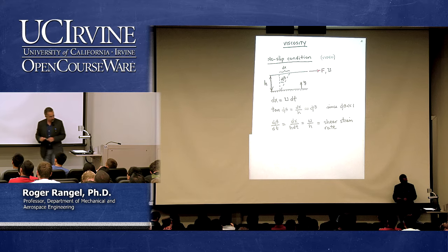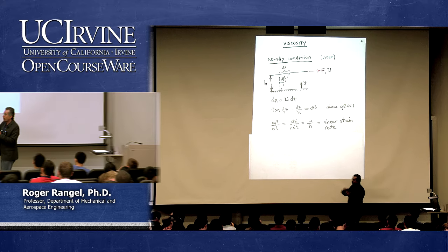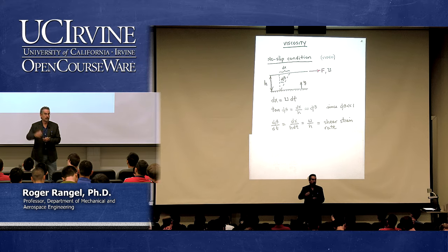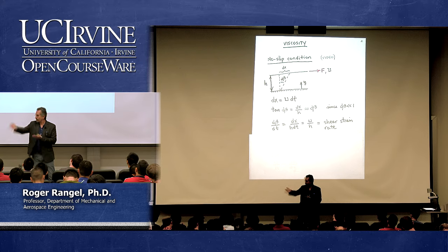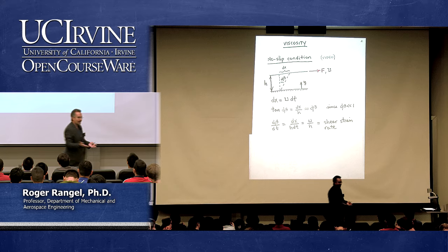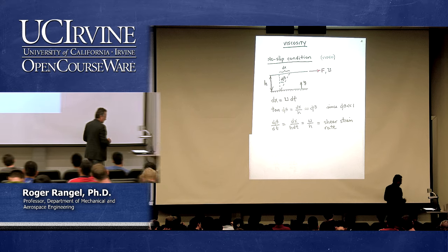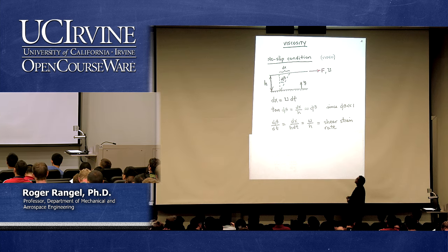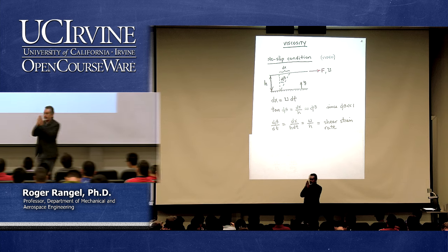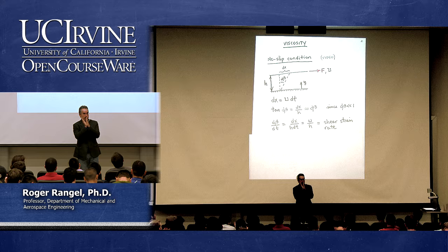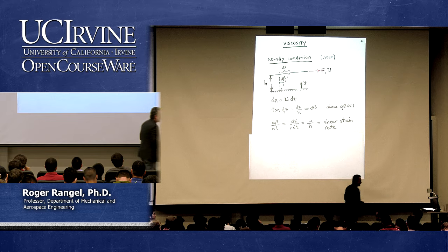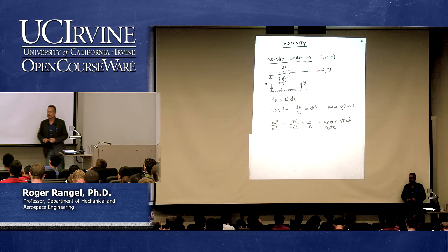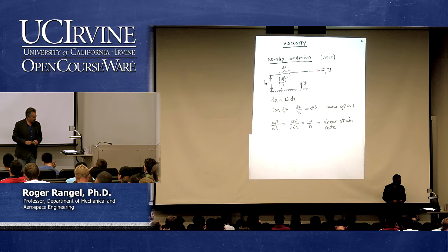We call that the shear strain rate, because that's a quantitative measure of the flow that we were talking about earlier. When I shear a fluid, it will flow. How do I quantify that flow? The best way to quantify it is by measuring these so-called shear strain rates. So I have a shear strain rate, which is the angle variation in time, d beta dt, and that is u over h. What are the units of a shear strain rate?